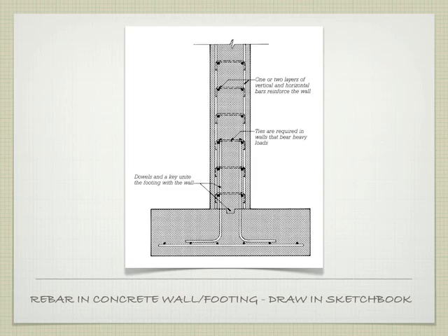On top of that, we're going to have our vertical reinforcing bars that would run here and here. And then we've got a variety of these little stirrups with the pieces that go this direction, which is basically forming the overall cage. So I'll draw in a few more little pieces here, with some little stirrups. That looks something like this. Make sense? The act of having to draw this out helps you to understand what's happening, which is why I'm asking you to draw it again, even if you printed the slides.